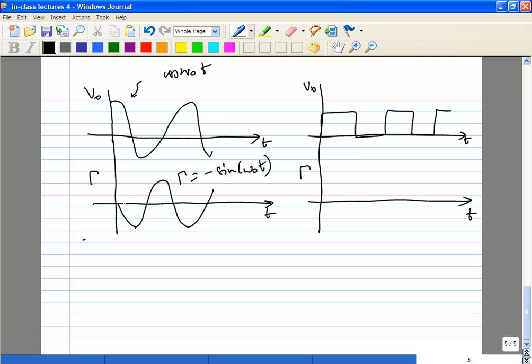How about the ring oscillator? So you'll get pulses right at the zero crossings. It will look like that. Again, if you differentiate the waveform, you'll get pulses at the zero crossings or the rise and fall instants.